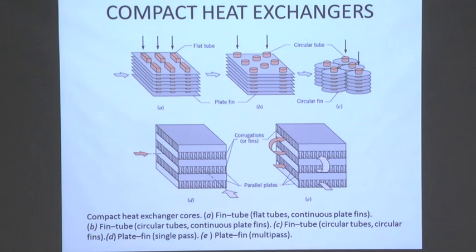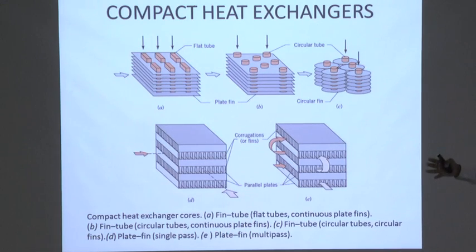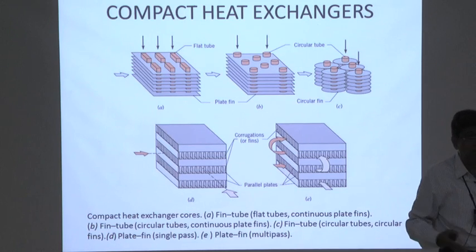How is it done? We know the rate of heat transfer for an imposed temperature field depends upon the surface area. So if you can make the surface area more, heat transfer rate is more, for which you know that the liquid is injected for heat transfer purpose in the form of spray. This is because if you split the liquid into spray of very minute drops, then the ratio of surface area to volume increases, which enhances for the same flow of liquid the heat transfer rate by enhancing the surface area. Similarly, if we can design a heat exchanger which provides a high surface area but a less volume, because the size is very important. If you tell me I have a big heat exchanger which has a big surface area, but it is so big that its volume is big, how can I accommodate this? Question of accommodation, the space requirement.